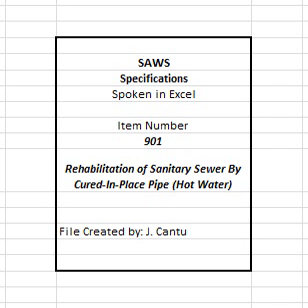4. Protection. A. The contractor shall provide for the general safety of workers, pedestrians, and traveling public throughout the project. Existing surface improvements and underground facilities and utilities shall also be protected. Damage caused by the contractor shall be repaired at his own expense. Protection to be provided shall include but not be limited to: B. Provide barricades, warning lights and signs for excavations created by point repairs and or excavation pits. Conform to requirements of TxDOT, City of San Antonio, Bexar County, or any other governing entity, and of contract documents.